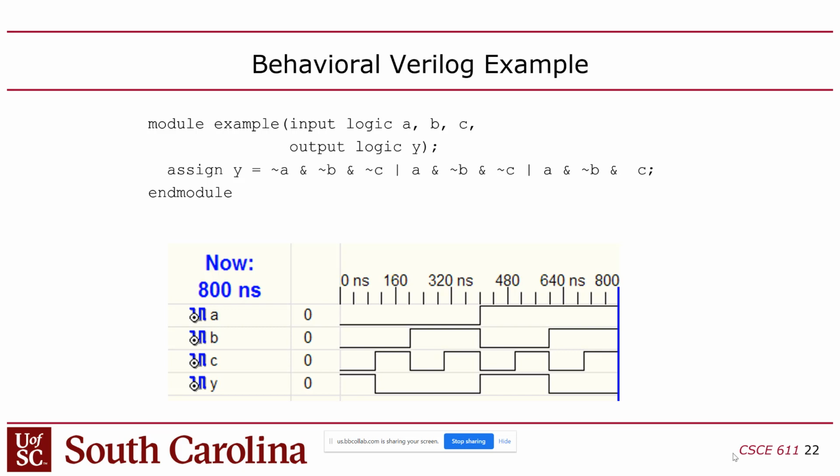So what's happening here is that you'll notice these are square waves, obviously, right? They're binary, they're square waves. Because this is not analog. If this were SPICE, they wouldn't be square waves; you'd see a curve there, right? But this is not SPICE. It's just a behavioral logic simulation. You don't want to simulate this stuff in SPICE. It takes way too long, if you can help it anyway.